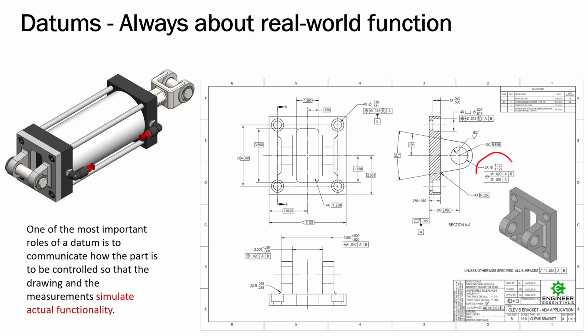And even going over to this composite tolerance over here, the first frame here is to A and B, right? So the rules of composite, the first frame is just like any other position. So it is being oriented to A and then located from B for these 2 holes. So quality has to lock it down in that same fashion.